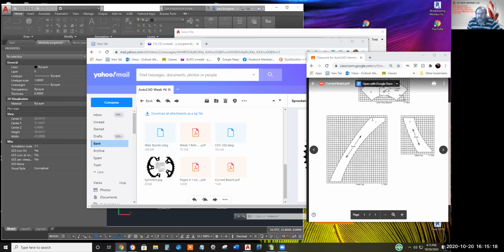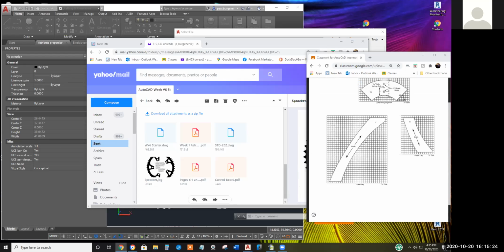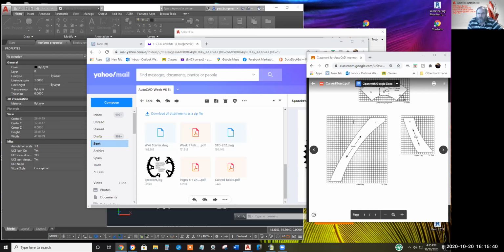The next step would be to save as a .dxf file. And this is getting out of my league, but with a DXF file, you can put it into a computer numeric controlled machine, and it'll literally cut this out of your wood or steel or whatever it's made of, just following the object by object, all the lines and arcs in the drawing file saved as a DXF.